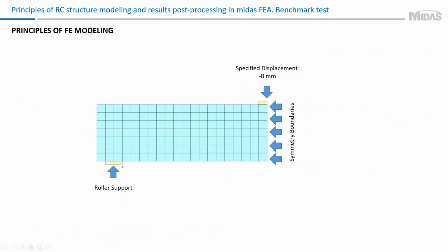Consider layers between boundaries. These layers will lighten the force and reaction transfer and will not affect the numerical solution. In this model, the layers have a lower stiffness than the concrete material. I used elastic material properties for the layers with a modulus of elasticity of wood.